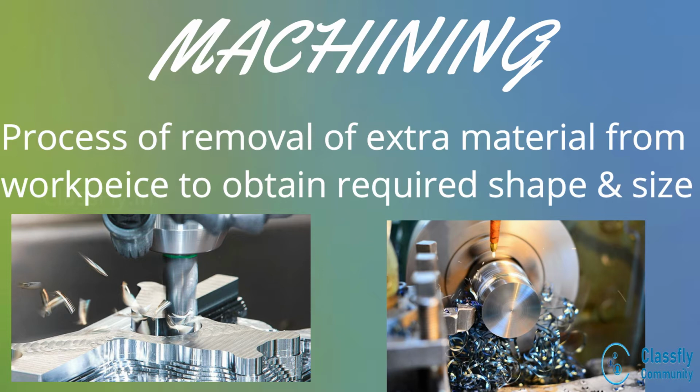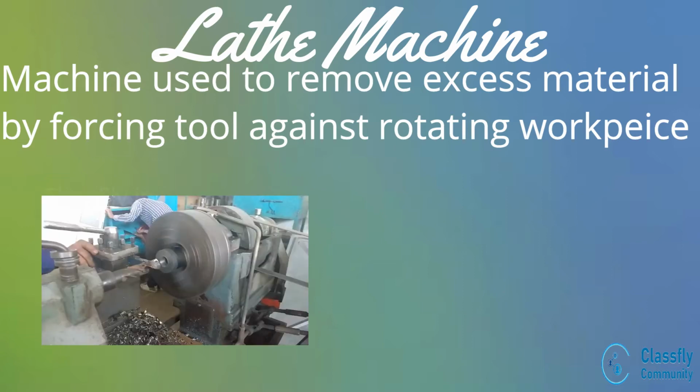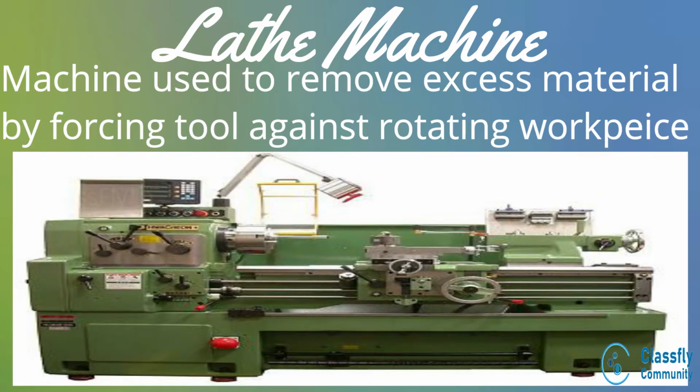Several machines are used for performing the various operations. Here, we are going to study some of the operations which are performed by a lathe, a drilling machine and a milling machine. So now, let us move on to lathes. Well, lathe is a machine tool which is used to remove excess of the material by forcing a cutting tool against a rotating workpiece. Well, these type of machines are also called turning machines since the workpiece is rotated between two center points. The lathe machine is known as mother of all machines as most of the machining operations can be performed in this machine.